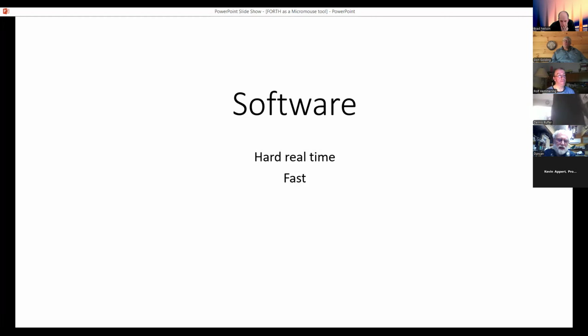Control software has to be fast. The response time of the mouse can be limited by software sampling rates. Sub-millisecond loop times are very desirable, but good electronics may reduce that requirement. In the limit, all the hardware control could be done by electronics or an FPGA, and the software would only need to run the solving algorithm and the user interface. But I don't know of any mice that do this. Software is weightless. That's in heaviness, not in time duration.